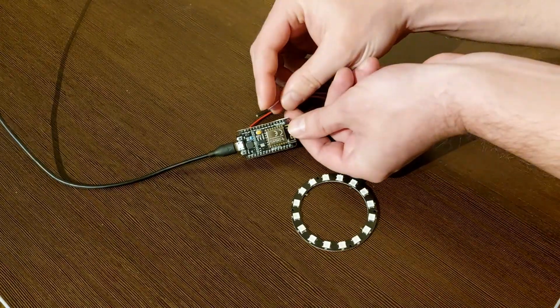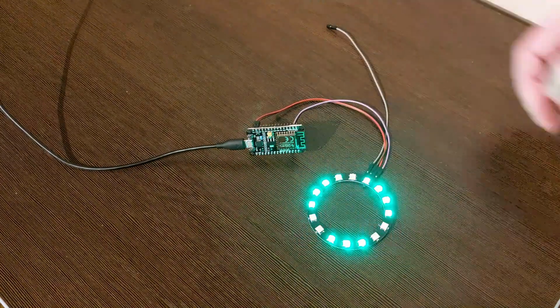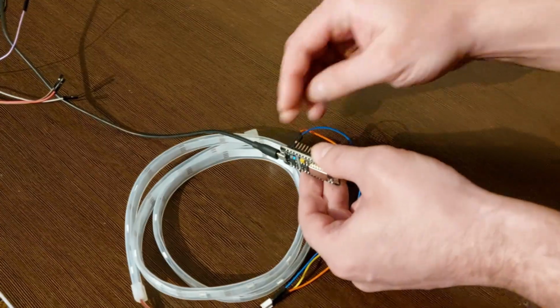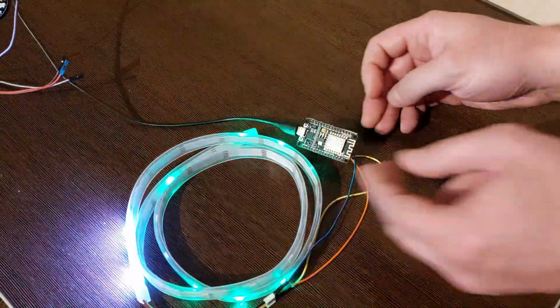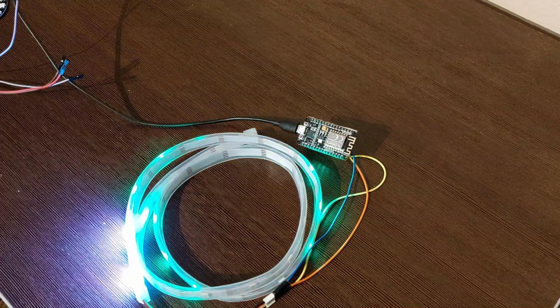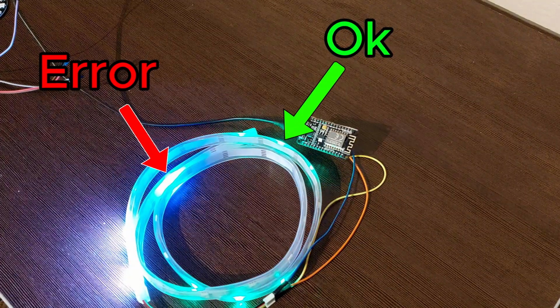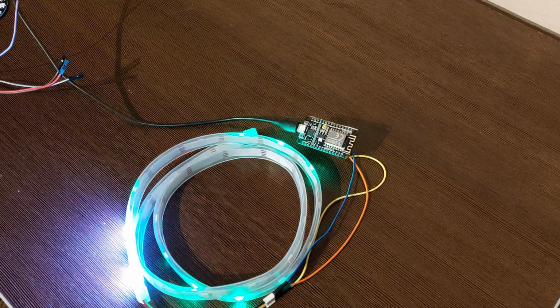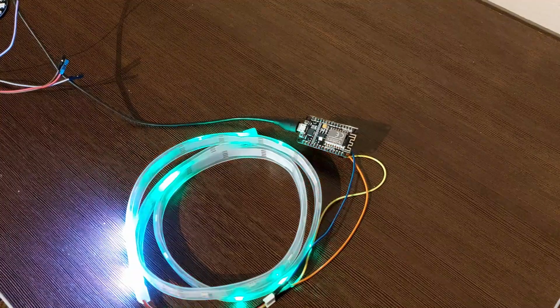So if you try to connect such a board directly to your strip, there is a chance that they will work just fine, but it may also happen that you will see something like this. The strip might be able to read some data correctly or display something absolutely random. So it's generally a good idea to use a logic level converter appropriate for your LED model.